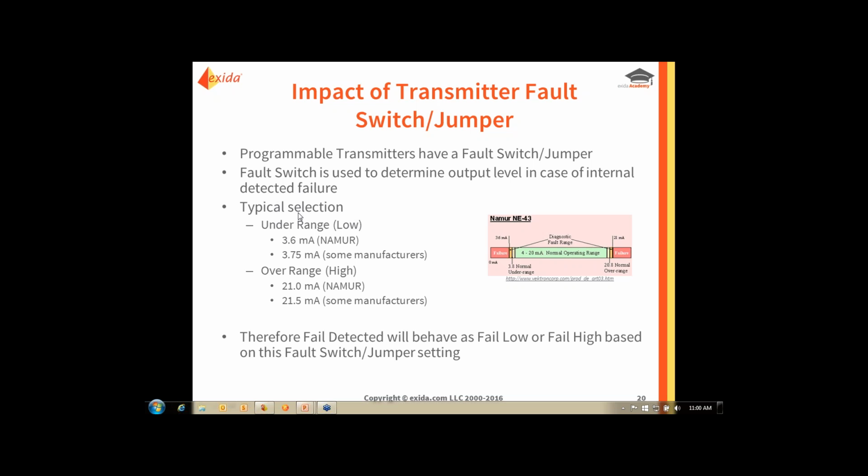Another question here is specific to external comparison. Is it within the SIS or external to the SIS and the DCS? Is it automatic or manual? Okay, we're getting to the implementation of some of the functionality here. I would say the standard says all diagnostics need to be implemented automatically in order for them to be credited as automatic diagnostics. So when we talk about external comparison, we are assuming that it is implemented automatically.